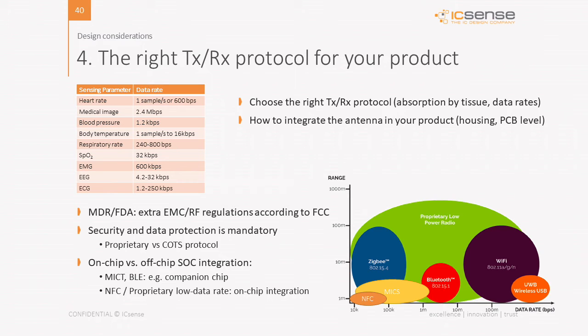More proprietary low-power radios are also applicable, and Bluetooth Low Energy is one of the ones also frequently used by customers. Keep in mind that the medical device regulation and the FDA require additional EMC and RF regulations, and security and data protection can also be mandatory.